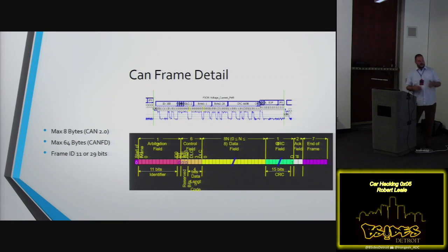Essentially what happens after the transmitter sends the data is there's a spot inside this field where the transmitter is now a receiver and the receivers are now the transmitter. All of the receivers will essentially raise their hand and say, yes, I got it, during this 1-bit time right here. Boom, they all say yes. But if one didn't get it, then at the next part of that bit it will say, no, I didn't get it. That's the chance for the nodes that didn't get it to actually say no. The ones that respond in the first bit say yes. The ones that raise their hand in the second bit say no, I didn't get it.